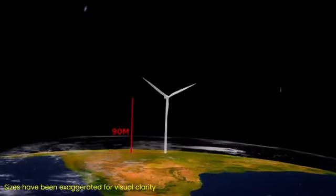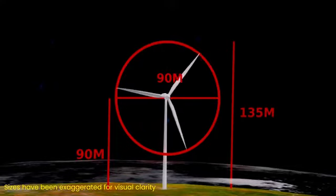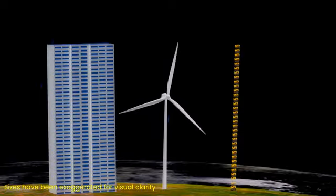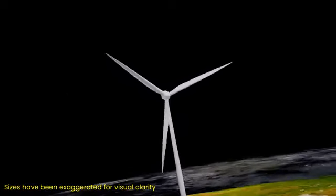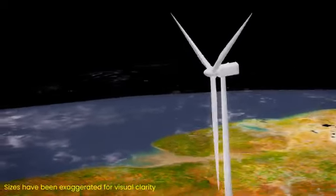It stands on a 90-meter tower and has a 90-meter rotor diameter, reaching a total tip height of 135 meters. To put that in perspective, that is roughly the height of 35 homes or a 40-story building. The blades rotate at speeds between 10 and 19 revolutions per minute, depending on wind conditions, usually settling around 14 to 17 revolutions per minute for rated power output.